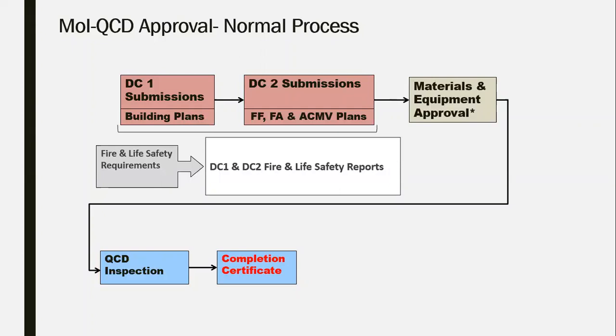In addition to the layout plans, you have to submit the single line diagram for the main firefighting system, how the electrical network will be, the medium voltage network, and a layout plan showing where the fire tank, the fire pump, and the fire command center will be located, and the access, showing the 2-hour fire rated and 1-hour fire rated areas, etc. And for electrical, the substation layout plan should be indicated as well.